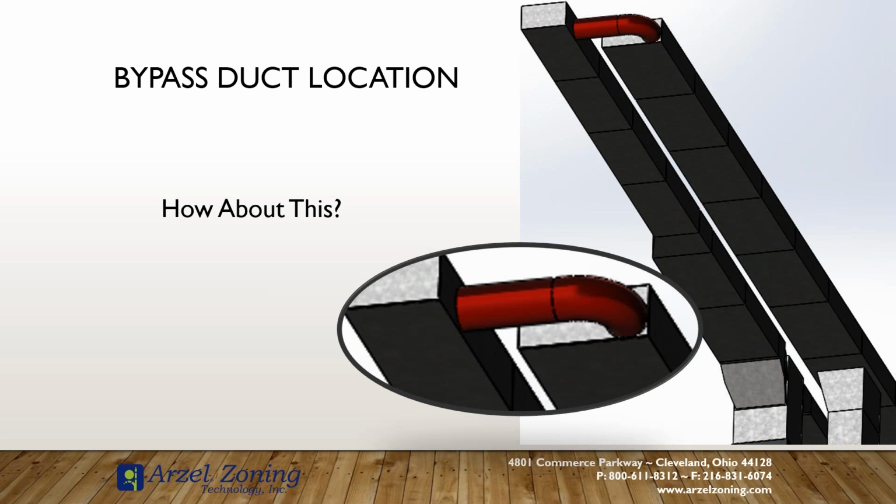And the reason being is because if you come off your end cap, you lose your back pressure in the system. So while this may very well be great for dumping excessive pressure, you're dumping that pressure into the point of lowest draw on your return air. So your return air is going to pull its greatest closer to the drop. It's going to pull its least furthest from the drop.